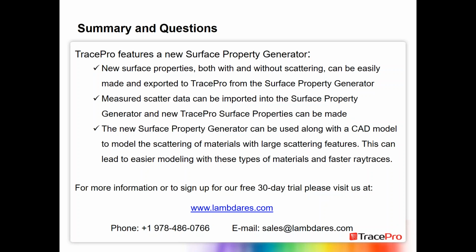But just as a little bit of a summary, TracePro now features a new surface property generator tool. This allows you to easily make and export new surface properties, both with and without scattering, and export them to TracePro using this tool. We can also import measured scatter data into the surface property generator and make new TracePro surface properties from that. And we can also use it in conjunction with something like a CAD model of an object that may not be something you could measure easily with a scatterometer, such as a material with large scattering features.